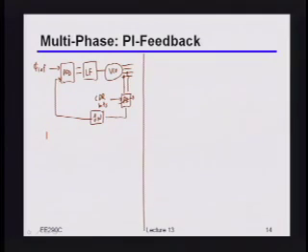Okay? So this particular idea, I believe, was first published by some people from IBM in Zurich. That's Thomas Toifl, and I believe this was in ISSCC 2005. So fairly shortly after the previous work that I mentioned. This indeed works pretty nicely, although notice it does introduce some extra high-speed hardware, in the sense that you have this phase interpolator that's still working at whatever the clock frequency actually is.